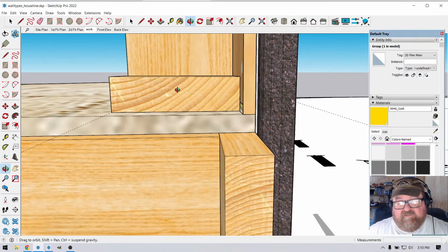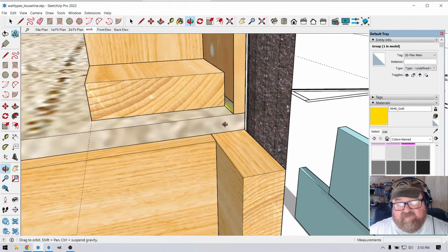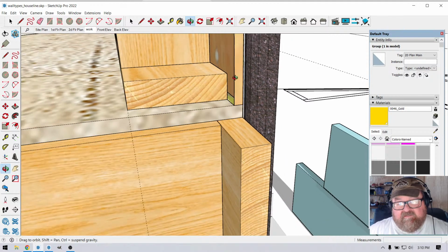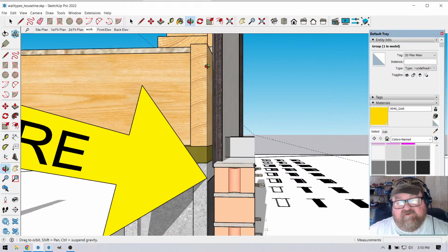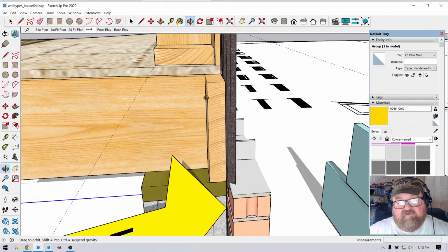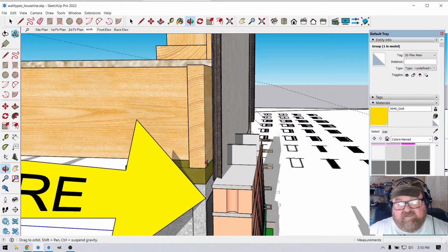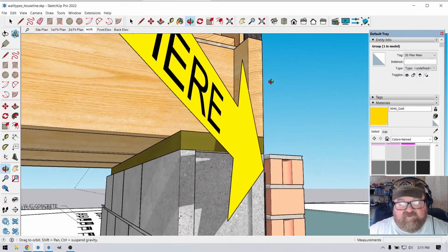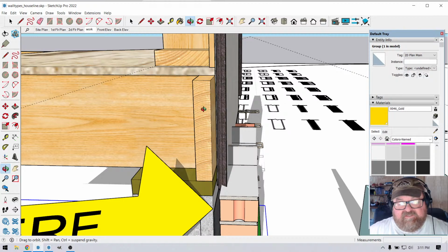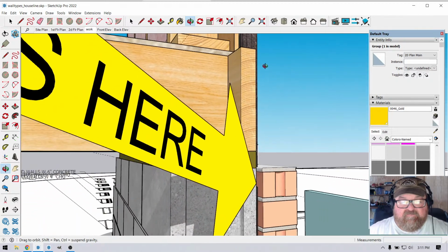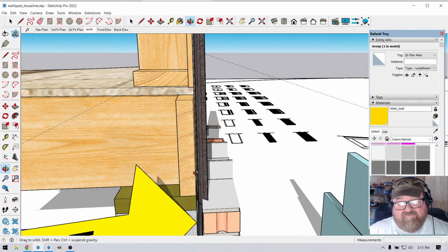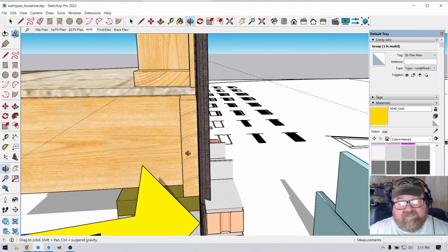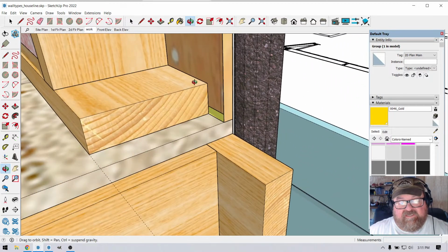A lot of people make the mistake of thinking that the framing goes on the house line and then the sheeting laps over this. But guess what you just did? You cursed yourself. Not only are you going to use more sheeting for no reason, there's no reason. This band, this header joist, this box sill, we have like 20 names for this thing, is thick enough that it doesn't need sheeting over the top of it.